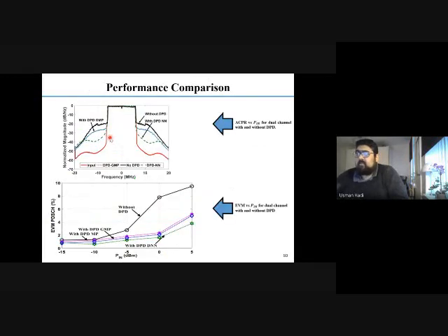Now you have previously seen that the generalized memory polynomial performs like this. Then we have the without-DPD black one. With this DPD-based neural network, we actually outperform GMP, which is the Volterra series method. With this green one, the neural network, we outperform GMP.